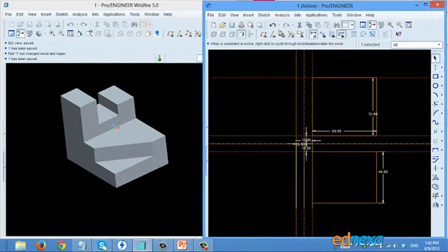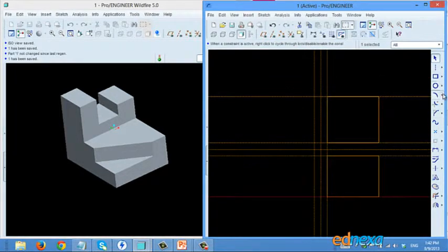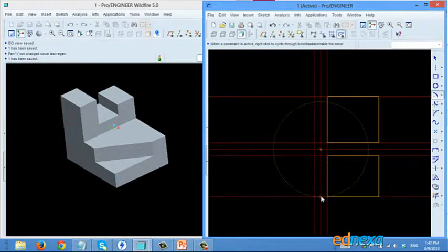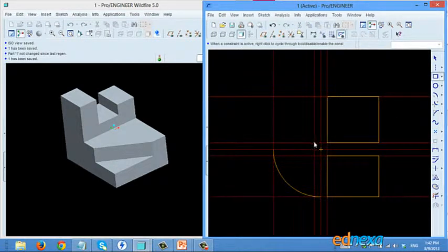So how will we draw the projection for it? First draw the projection through this line, and we'll see the arc method now. Draw your arc by making this axis origin the center, and draw from this vertical axis till the horizontal axis, and do not forget to project this from here and draw the view from here.